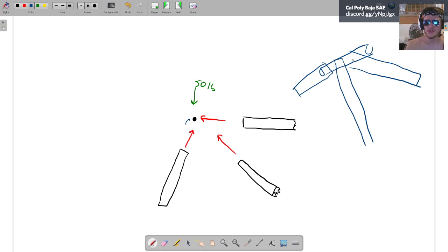And we can see on this pin that if I put a force going straight down, it must be constrained by all of these beams, and because we're assuming it's static, it has to be in that direction. If it's not in that direction, let's say if this beam were to resist in this direction, well, that means we're suddenly putting a moment on this beam. So we're going to try and rotate that beam, right?